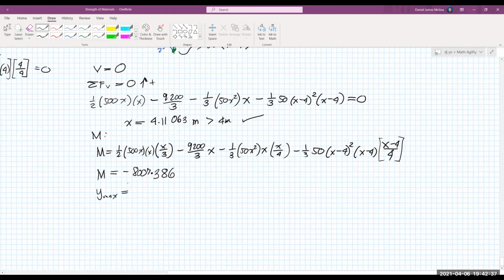Since EI is constant all throughout the beam, our moment diagram by parts is the same as the M over EI diagram. I forgot to mention that actually. So EI is constant, therefore the moment diagram is the same as the M over EI diagram. If the value of EI of the given beam is not constant all throughout, then we must draw the M over EI diagram first so that we could have our conjugate beam.